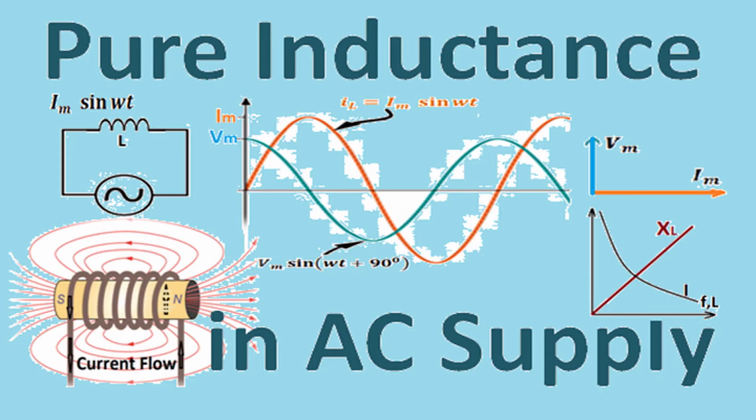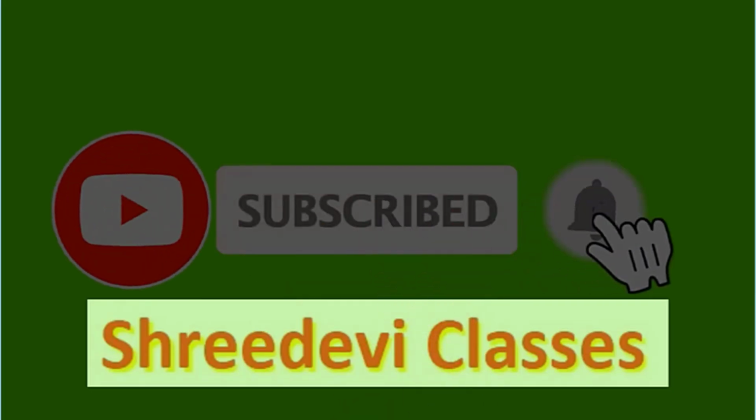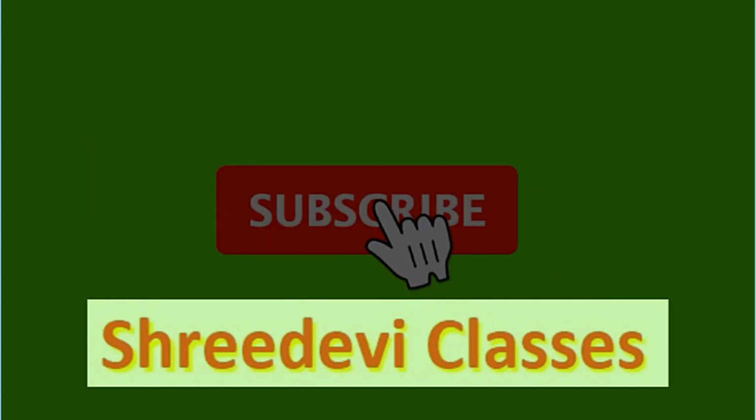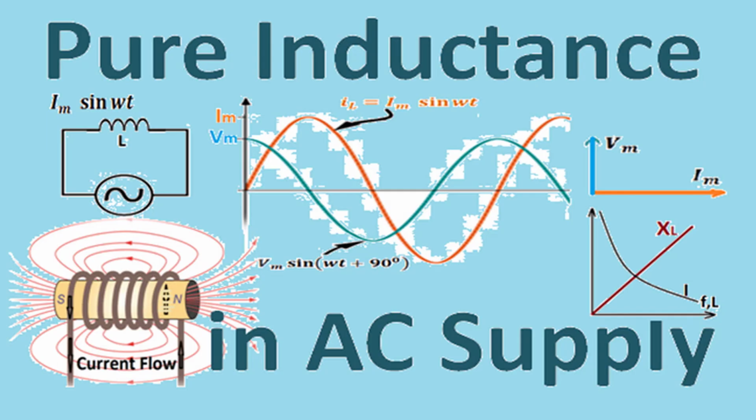We hope this learning video has explained each and every learning aspect of pure inductance behavior in alternating current supply. Now with the VL equal to L di by dt relation, you could understand that in pure inductance, current lags voltage by 90 degrees, and in those conditions, average power in the inductor is 0, but there exists reactive power, and the inductor stores energy when current increases and releases the same stored energy when current decreases.